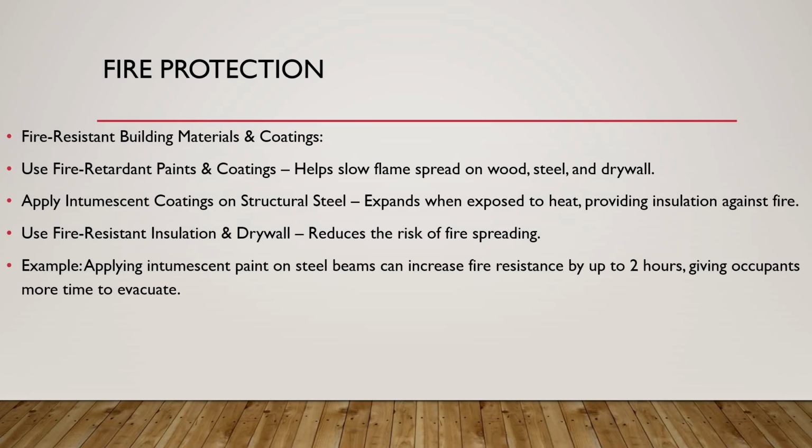Use fire-resistant insulation in drywall. This will reduce the risk of fire spreading. An example of this would be applying intumescent paint on steel beams. Pretty much can increase fire resistance by up to 2 hours, giving occupants more time to evacuate.